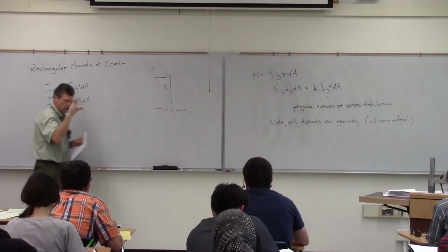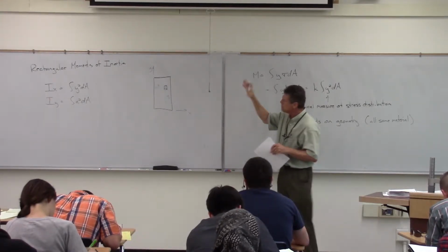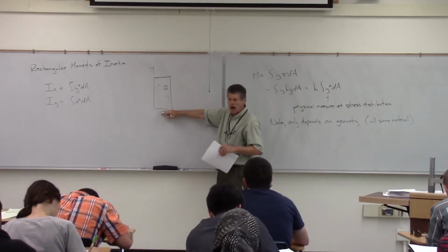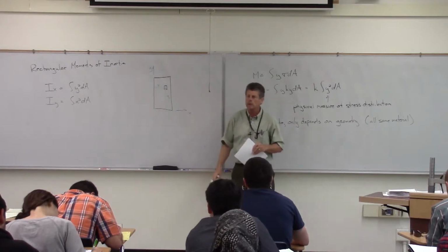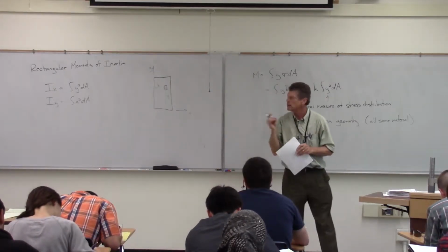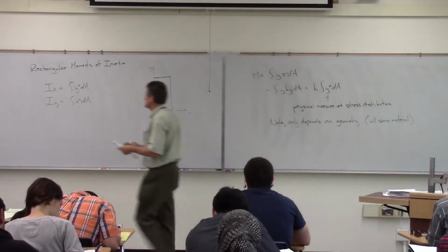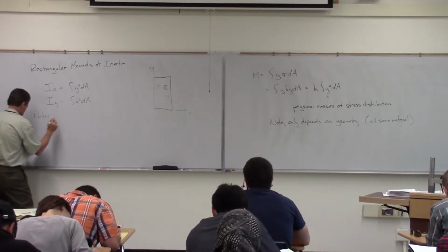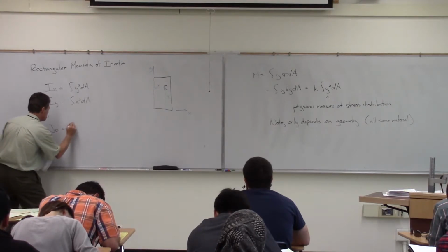And again, just keeping in terms of our Cartesian system, keep in mind that moments are always going to be those perpendiculars. So if I'm measuring an I about the x-axis, I'm going to have a y moment arm. Vice versa, if I'm doing an I of y calculation, then I'm going to be looking for x as my moment arm. And then there's a third one. And why your author uses J, I don't know.